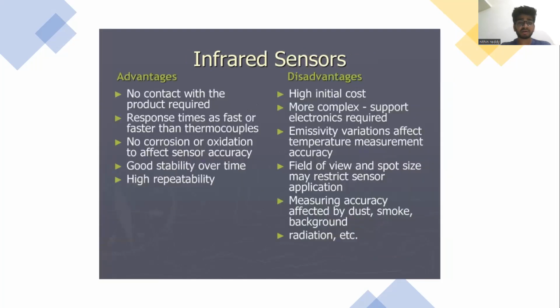Its advantages are no contact with the product required, response times faster than thermocouples, no corrosion or oxidation to affect sensor accuracy, good stability over time, high repeatability.